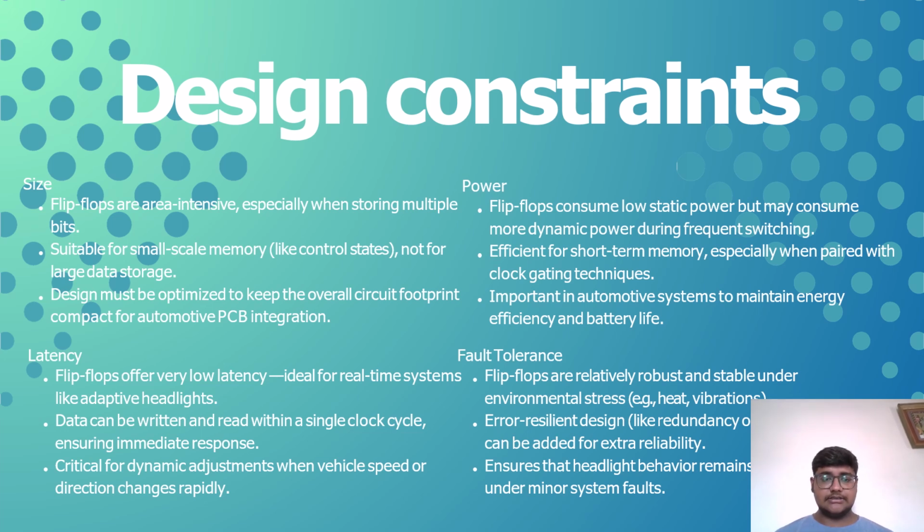Flip-flops are area intensive, especially while storing multiple bits, so they are suitable for small memory but not for large data storage. Flip-flops offer very low latency, ideal for real-time systems like adaptive headlights. Data can be written and read within a single clock cycle, ensuring immediate response. This is critical for dynamic adjustments when vehicle speed or direction changes rapidly.